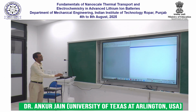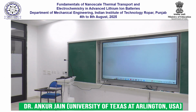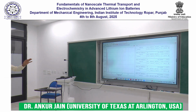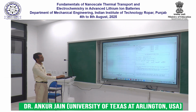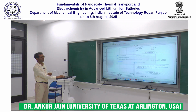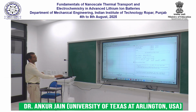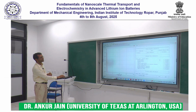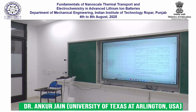So I hit the start run button, and now it's doing all the mathematical mumbo jumbo in the background without really telling me much about it. So all those setting up the number of equations that we talked about and solving those equations is now beginning to happen. And it is plotting the residual. Oh, and it happened very quickly. My residual criteria was reached within a few iterations. Actually, it finished 200 iterations very quickly.